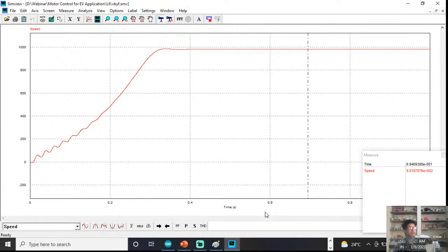In an asynchronous machine, definitely it will produce torque when it deviates, when it is slightly away from its synchronous speed. If you remember the speed torque characteristics, if the speed is exactly the synchronous speed, then the torque is 0. That means if slip is 0, then torque is also 0. And we learned the instantaneous torque equation. There, if you put slip 0, then your torque will also become 0.